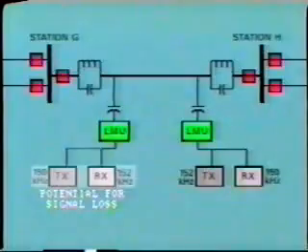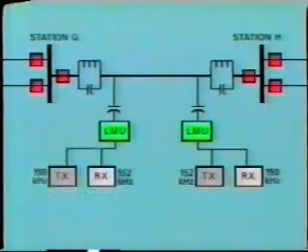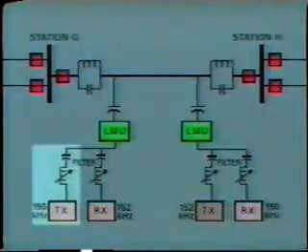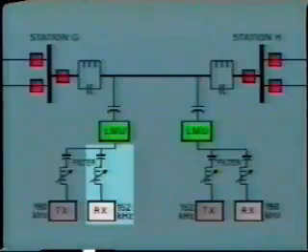But with this arrangement, there is the potential for significant signal loss and interference from transmitter to receiver at each end. But how come? Aren't the transmitters and receivers fitted with filters tuned to their specific channel frequency? For example, 150 kilohertz on this transmitter and 152 kilohertz on this coupled receiver.